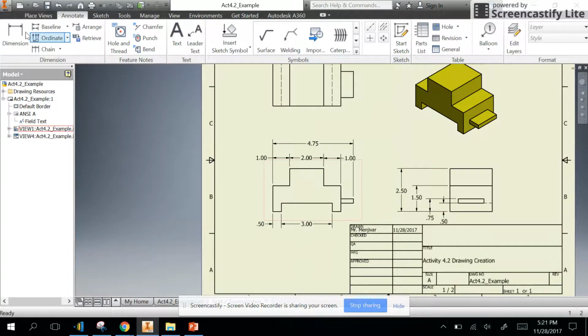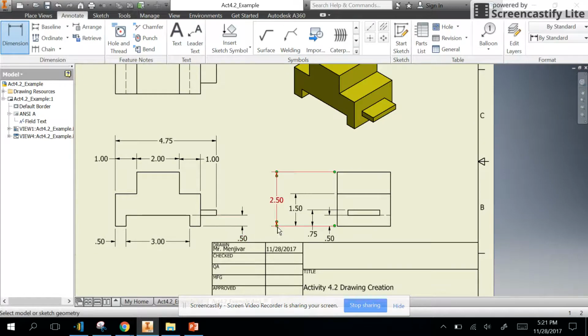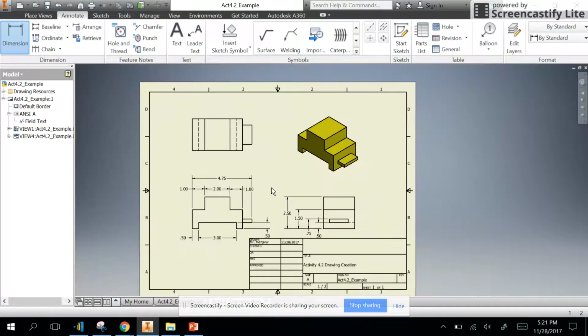No, not quite, actually. Just because I know that this wing is 0.5 up and it looks like the hidden line is at the same height, I don't actually know that this is 0.5. Some folks are going to confuse this 0.5 with this 0.5 and think they're the same, but they're really telling two different pieces of information. So now I'm done with the heights. I can move on to depths. I'll do that over here.